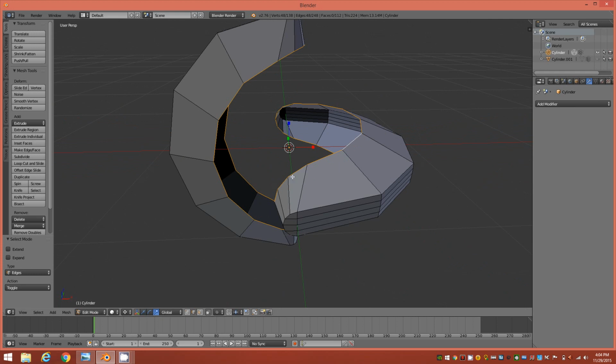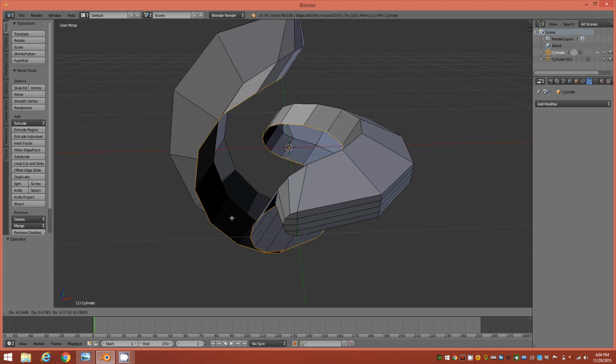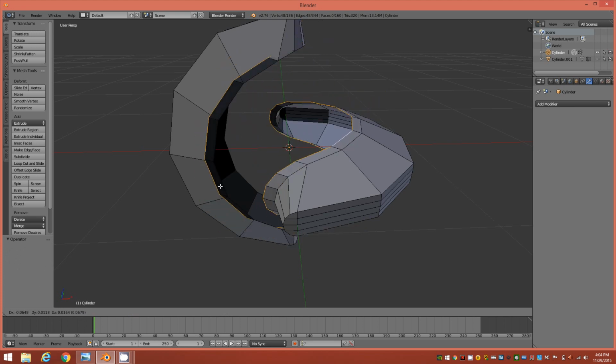With the scale manipulator activated and the 3D cursor as our pivot point, we're going to tap E on the keyboard to activate extrude. But what we're going to do is right click, and that activated the extrude, but it didn't actually extrude anything. Let me do that again. I'm tapping E, and normally you can move around and pull out edges or faces, but that's not what we want to do.